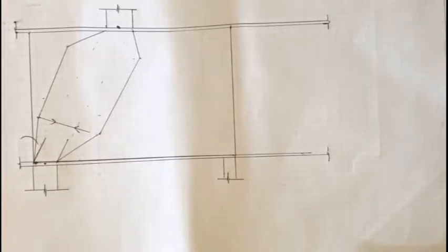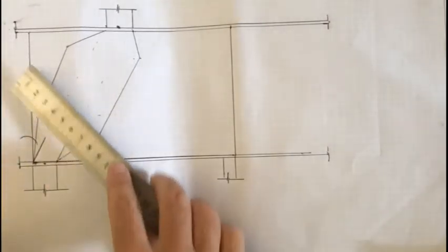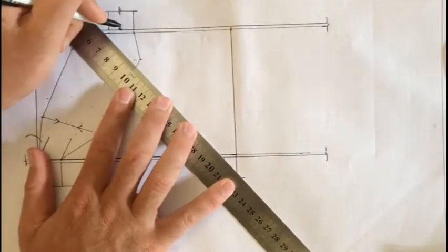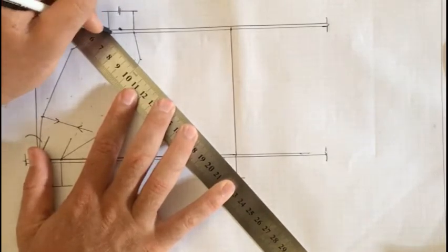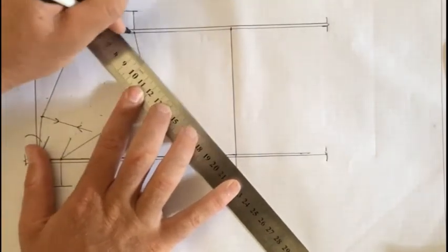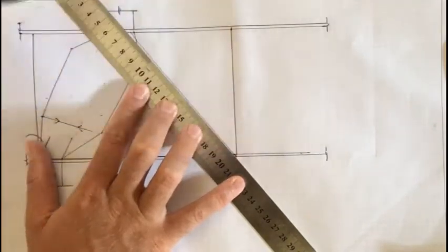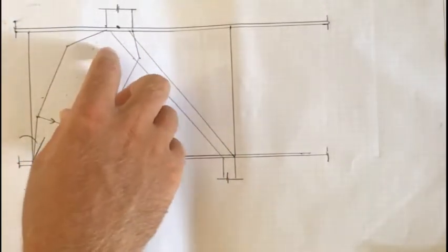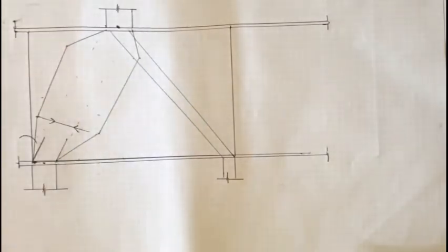On this side, if we look at an idealized parallel sided strut like this, it moves in just straight, and if we looked at it like that, no tensile forces are developed. But if you look at clause 7.2.1, prismatic struts shall be used only where their compressive stress field cannot diverge. So this is generally the case we'll be using.